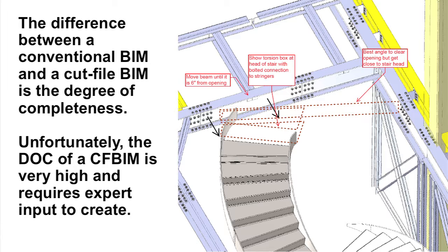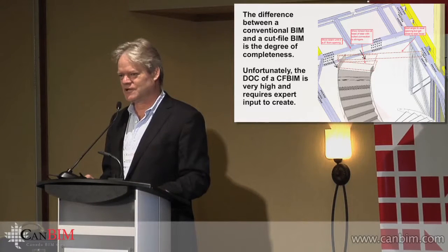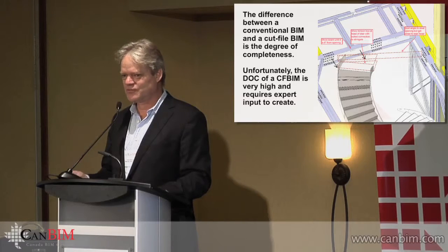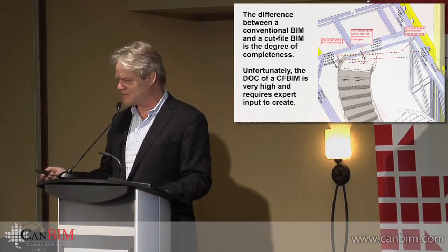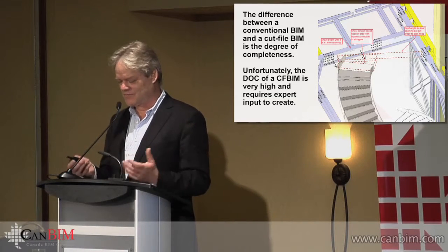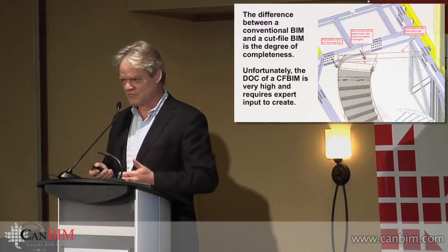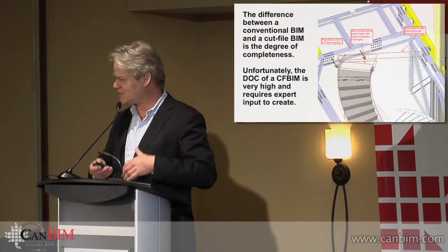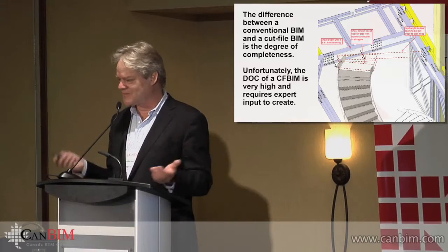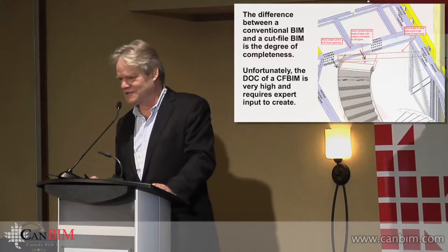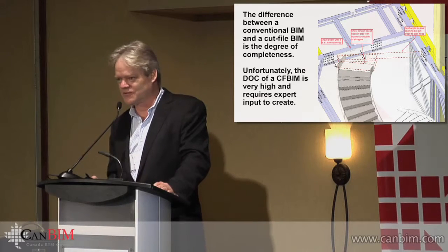So the degree of completeness of a cut file BIM is very high, A, and B, it requires expert input to create. So all of the folks that you've seen up here earlier today, all of their input is required on the cranes, on what's feasible in terms of connections, what's feasible in terms of piping, what's feasible in terms of airflow, of insulation, everything else. You need all of that information before you can create a fully complete cut file level BIM.